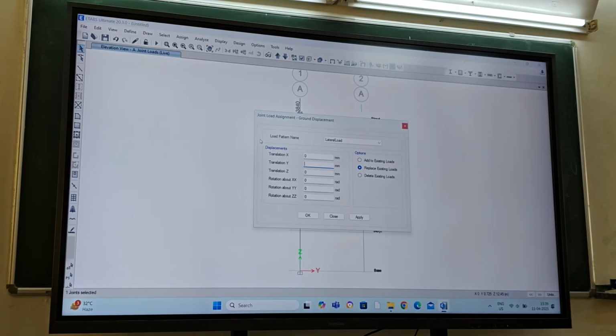Just to go beyond the collapse range also. That means 240 mm, whatever you got, is the displacement range where the column will show the collapse. Okay. So to show the complete behavior beyond the collapse also, it will go to the softening range after the peak point. So you can give higher displacement also. So let us say I'll push this column up to 500 mm displacement and see what happens.